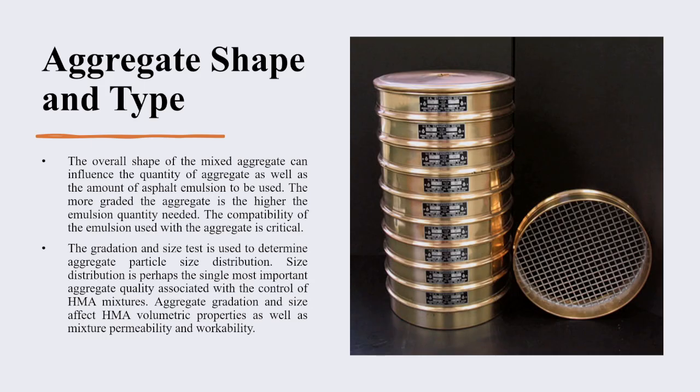Now when it comes to asphalt, it depends. Some organizations in the US consider number 8, others consider number 10, to be the sieve that distinguishes between coarse and fine in the asphalt industry. So specs are not the same.